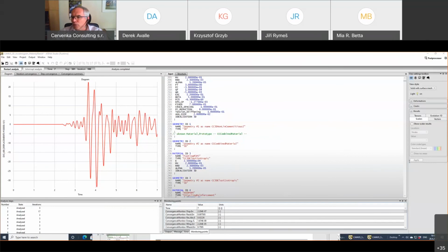Seismic mass included, that means D plus 0.3 L. Yes, we already answered the question from the applied dead load and live loads in the previous interval. Exactly. In the previous intervals where I was applying the dead load and live load, I would of course apply the live load only up to the level that we need to consider in the seismic analysis.